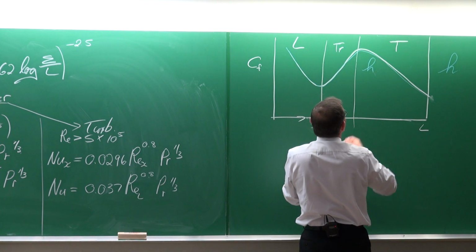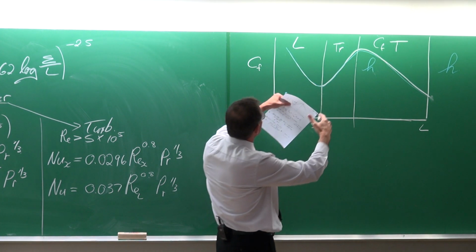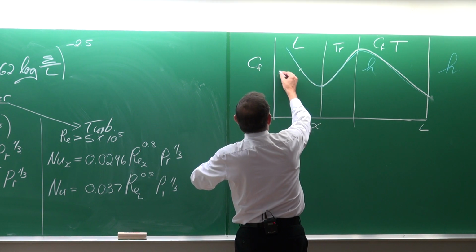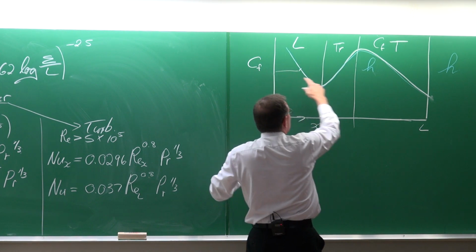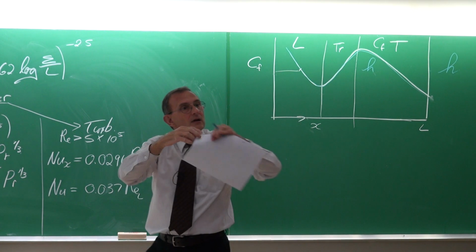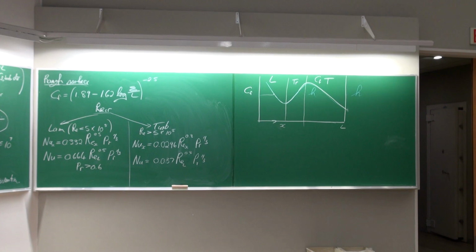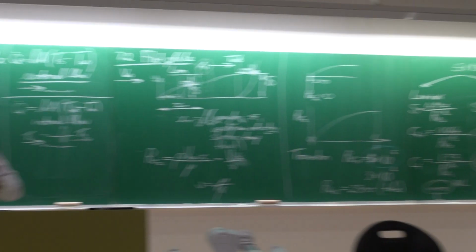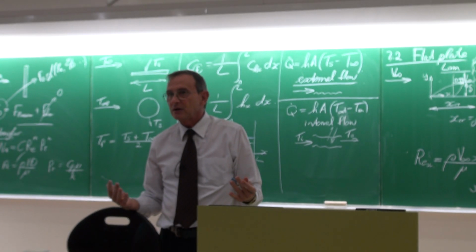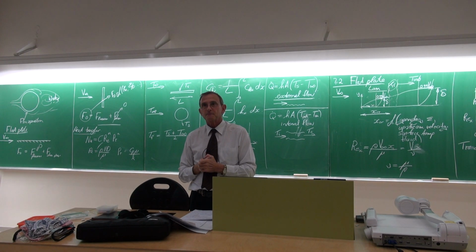That's the heat transfer results, and that is the CF values. The scale in terms of this value, which is maybe 0.5 here, might not be 0.5 there with the heat transfer coefficient, but the general curve of the two are exactly the same, and again it shows the Reynolds analogy that we've done in the previous chapter between fluid mechanics and heat transfer.